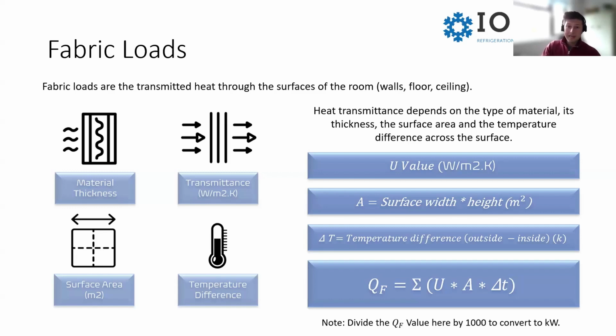Our temperature difference, for any room we do, will be the outside condition at its worst case. If we're in a fairly airy warehouse, back of house area for a supermarket, for example, you may only get a temperature maximum of 25 degrees there. If it's a very, very warm space or air builds up or machinery is kicking heat into that area as well, it might be 32 degrees. Our inside temperature is going to be our design condition.